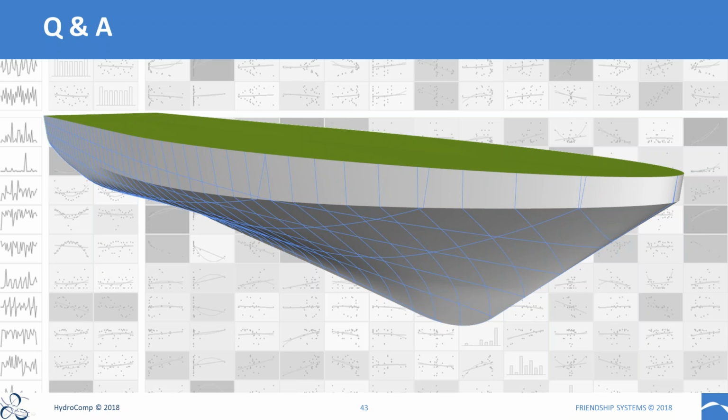Then we have another question from Alvaro, which is, are the surfaces generated as NURBS surfaces in CAESES? So the answer is yes. The modeling kernel, the CAD kernel that we have at the basis of CAESES is a NURBS kernel. So everything that is generated is NURBS geometry and will be exported into an IGES or STEP format and so on as a NURBS surface.